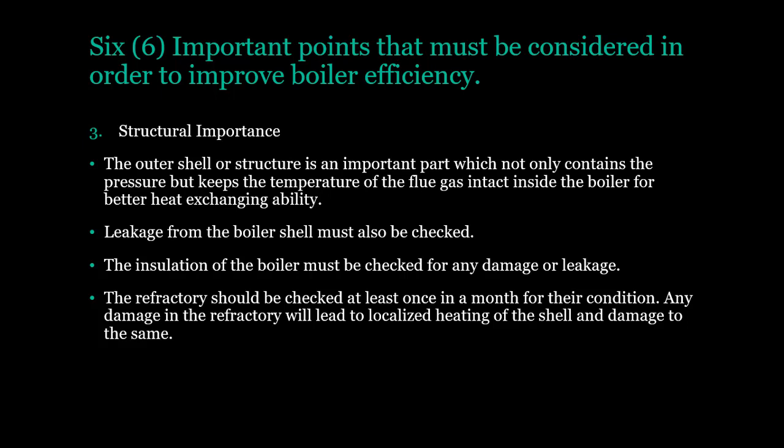The insulation of the boiler must be checked for any damage or leakage. The refractory should be checked at least once in a month for its condition. Any damage in the refractory will lead to localized heating of the shell and damage to the same.